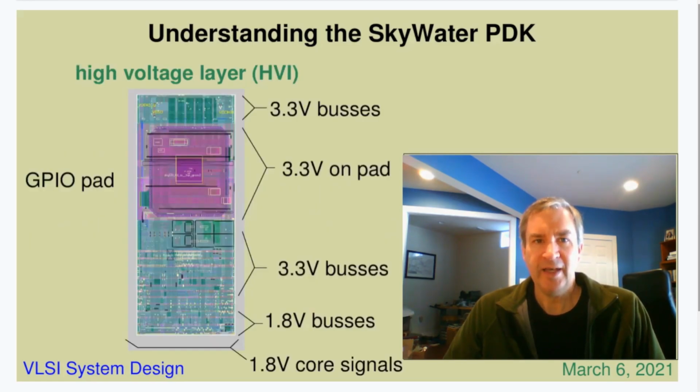The HVI layer is a high voltage implant. It has more than one use. For one, an end-well implanted with HVI is tolerant to higher voltage levels. The mask is also used to grow additional insulation under the gates of MOSFET transistors, forming what is known as a thick oxide gate transistor.